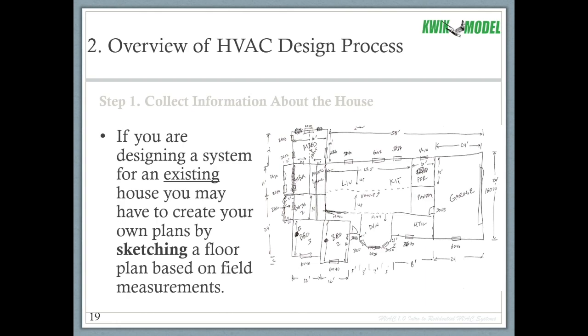If you are designing a system for an existing house, you might have to create your own plans by sketching a floor plan based on field measurements. So you might have to go out to the house with a tape measure and measure the perimeter of the house and draw the floor plan, and hopefully it looks a little better than this one. But the good news is if you have something like this with all the information that you need, you can do load calculations with something even kind of sloppy like this.